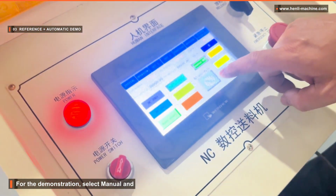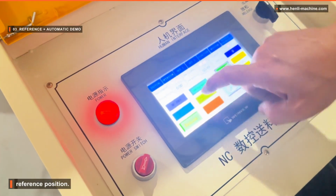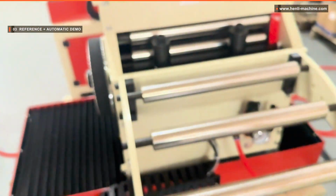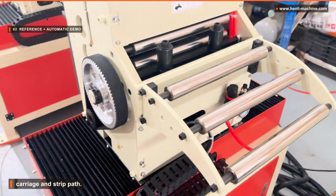For the demonstration, select Manual and press Return to bring the carriage to its reference position. Jog the carriage to the required right side start, watching the mechanism to confirm travel direction. Confirm the starting position, select Auto and Start. Keep clear of the carriage and strip path.